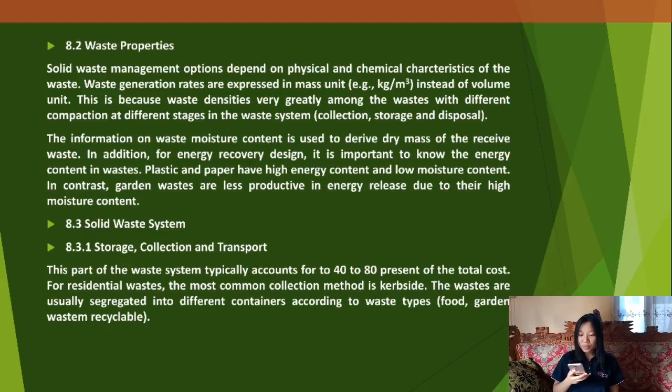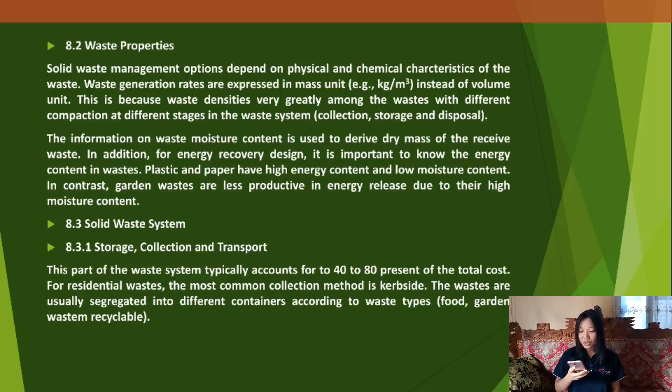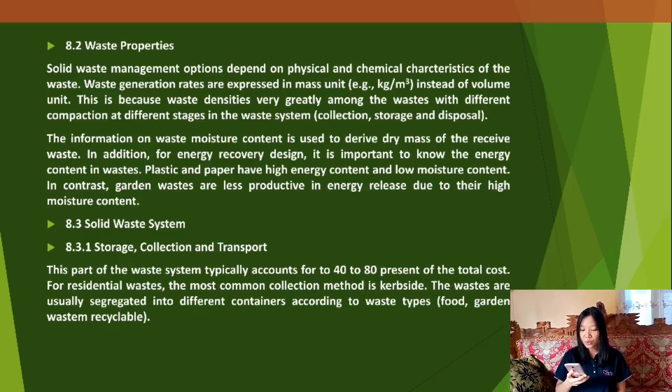8.2 Waste properties. Solid waste management options depend on physical and chemical characteristics of the waste. Waste generation rates are expressed in mass unit, e.g., kilogram, instead of volume unit such as meter cubed. This is because waste densities vary greatly among the waste with different compaction at different stages in the waste system: collection, storage, and disposal. The information on waste moisture content is used to derive dry mass of the received waste.